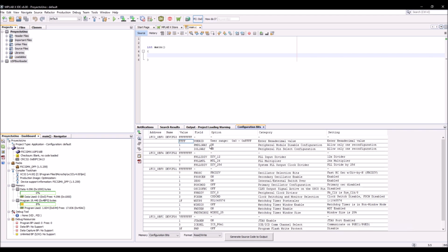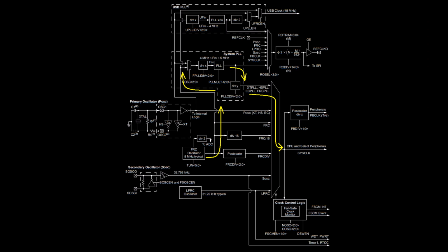The other bits that are related to the remapping of the terminals and calibration of peripherals are not important in this project since only the microcontroller ports will be used. The second configuration word, DEVCFG2, is important to analyze, and it is related to the oscillator, and my objective is to work with the internal 8 MHz oscillator.